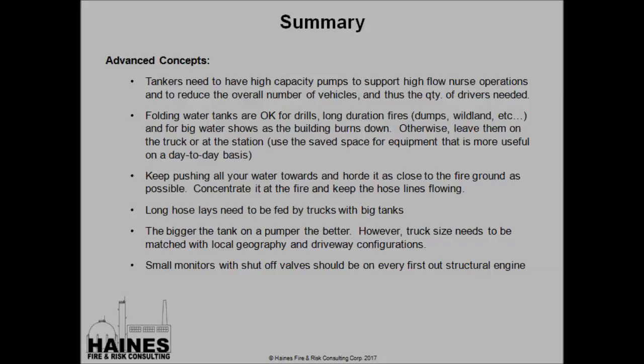I really firmly believe that small monitors with shutoff valves should be on every first out structural engine. They give you so much ability to put a very large amount of water on the fire very quickly and to shut it down very quickly so that you don't waste water.